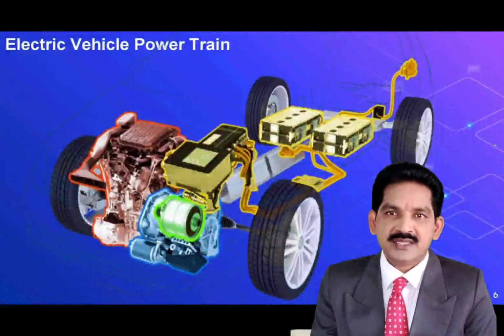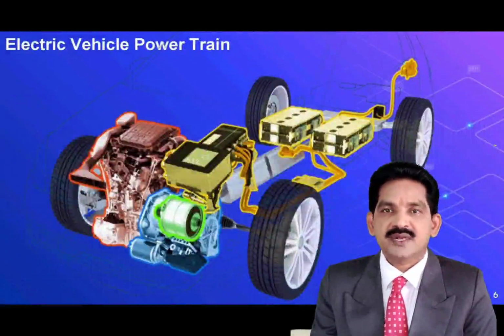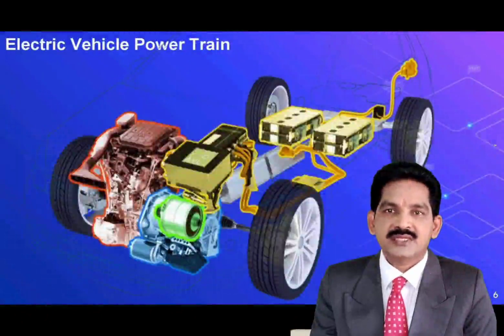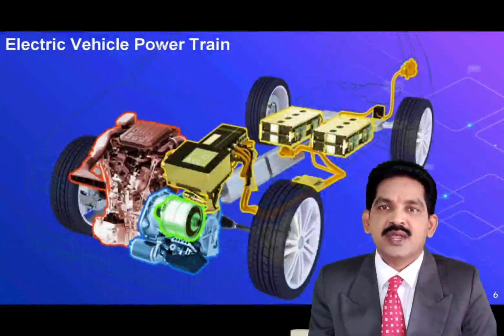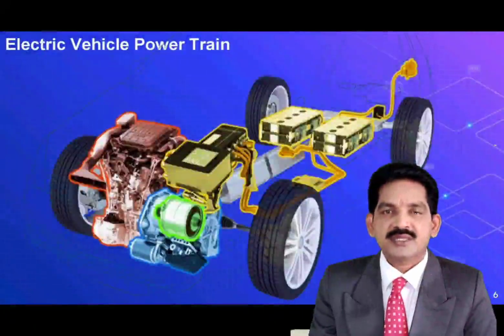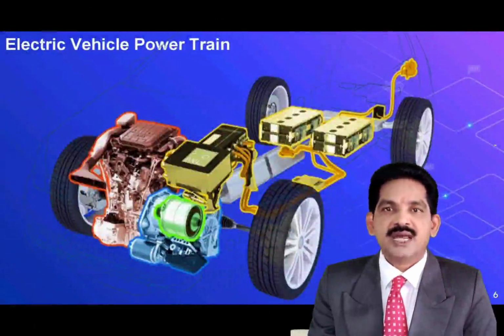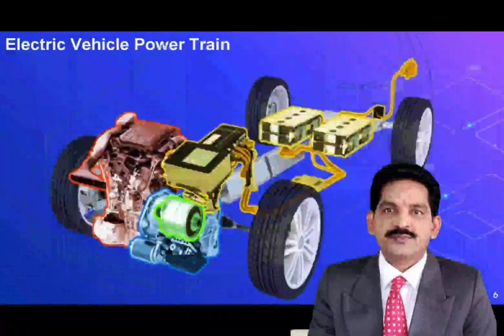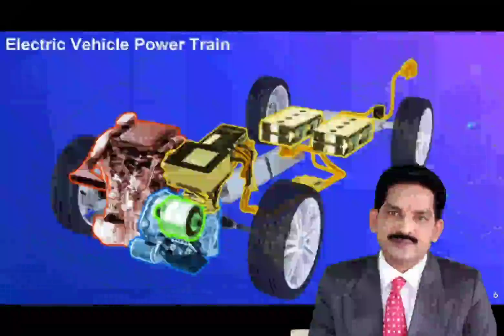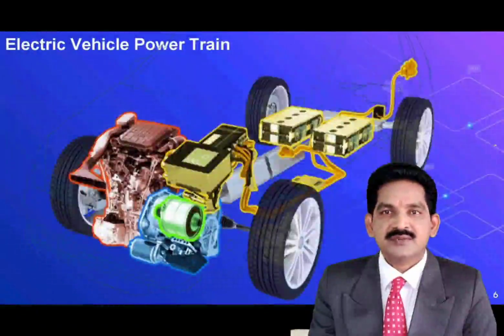The electric vehicle drivetrain alternatives based on the power source configuration. Besides the variations in the electric propulsion, there are other electric vehicle configurations due to variations in energy sources. There are 5 configurations possible. Configuration 1 is a simple battery powered configuration. The battery may be distributed around the vehicle, packed together at the vehicle back, or located beneath the vehicle chassis.